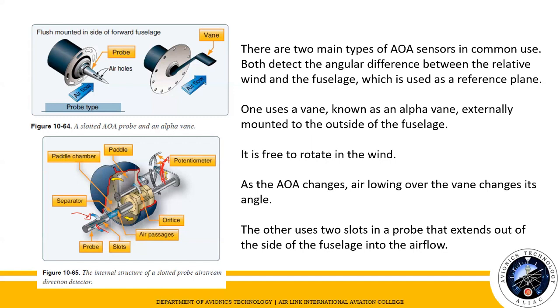So electrical switches are actuated in the AOA indicator at various preset AOA to activate the motor that drives an unbalanced weight ring causing the column to shake. Ganun din sa yoke. So regardless of the many existing variations for warning of an impending stall, the AOA system triggers all the stall warnings in high-performance aircraft.